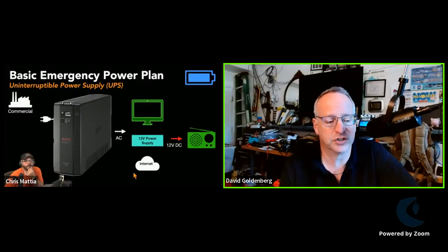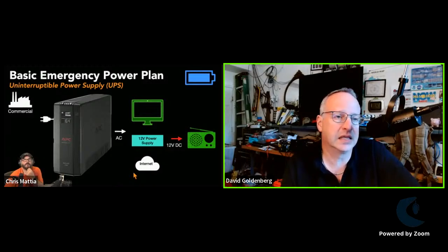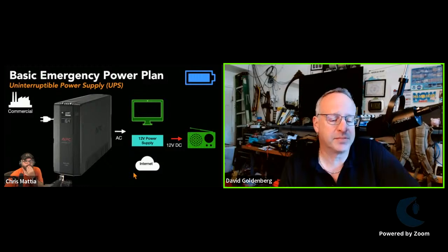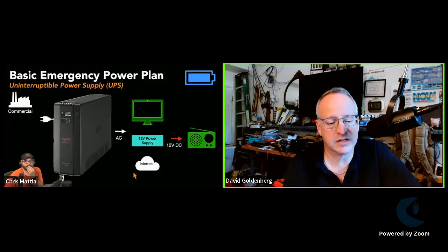The device hopefully should just be running on its own all the time. As Dan stated, for the gateway that I have set up behind me, the UPS is plugged into the power supply. The power supply is charging the battery. When the UPS dies, yes, it will stop charging the battery, but the battery is plugged into the radio, and the radio is going to continue running while that battery lasts. The laptop is going to continue running off its battery until that goes.